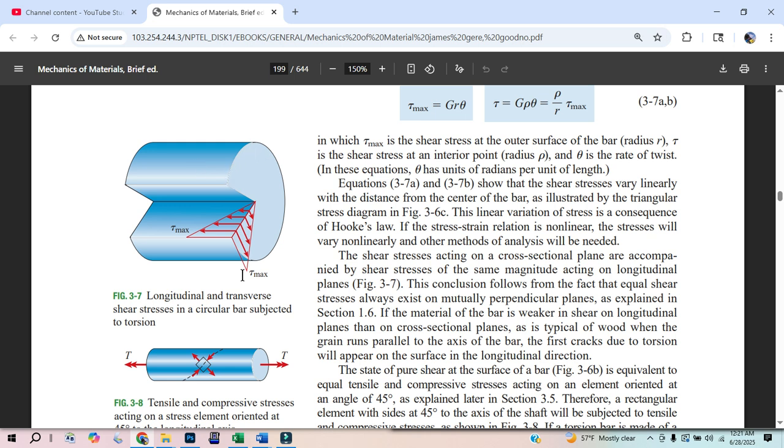One of the rings goes down, the other stays put, and we get a diamond shape to form. 2 of those molecules are getting stretched out, 2 are getting compressed, so we're understanding what shear is. And we're understanding that an angle gets formed. So that diamond shape is the angle. That angle is indicative of how far those 2 diagonals are getting tensioned and how much these are getting compressed. That is what's holding the force.